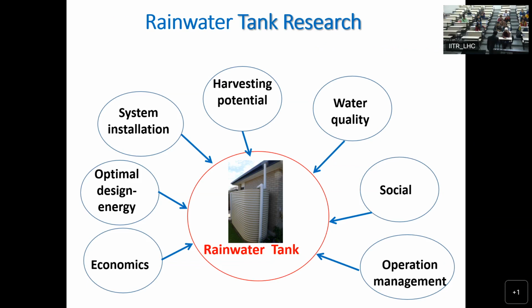What you're looking at, over the whole year, is how much water has been coming in and how much water is being used. So there will be days when there is no rainwater available in the tank. So you are doing actual calculations based on the availability of water in the tank. And then this size of the rainwater tank,